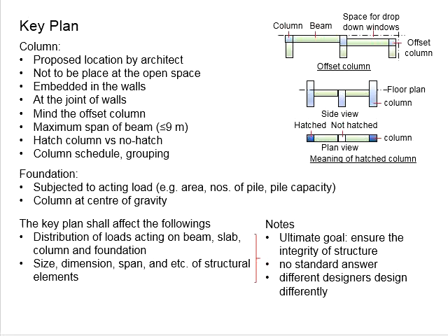Let's say now you are talking about a single layer wall, where the width of the brick wall is 115, plus the plastering at both sides of the wall. The width of the column to be embedded within the wall will be more or less 150 mm. You know that there are concerns also when the width of the column is smaller than that.